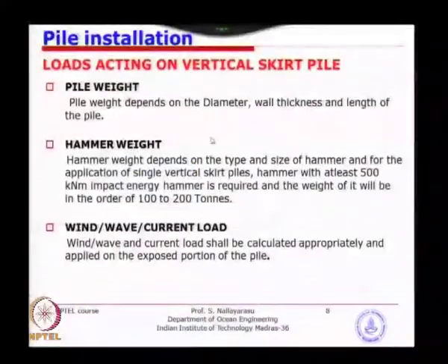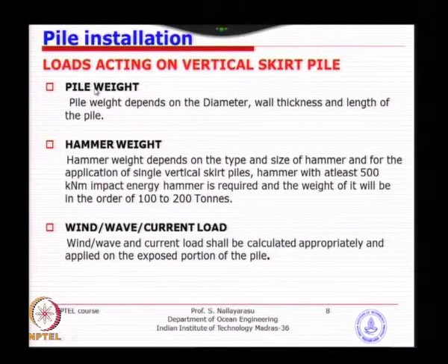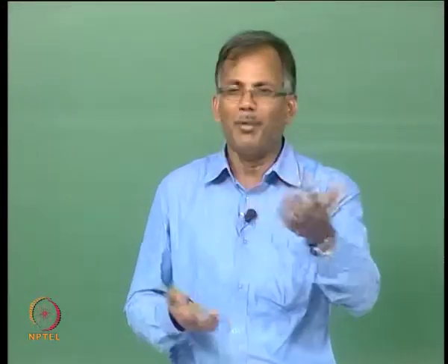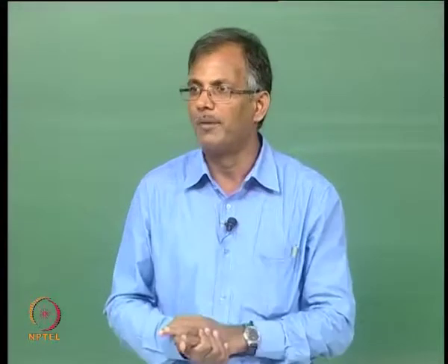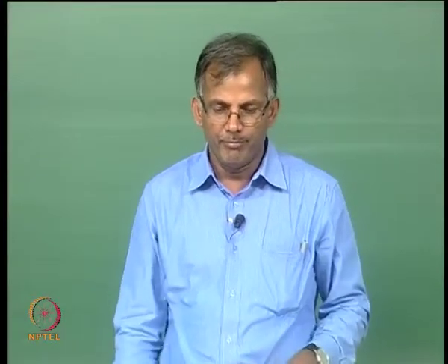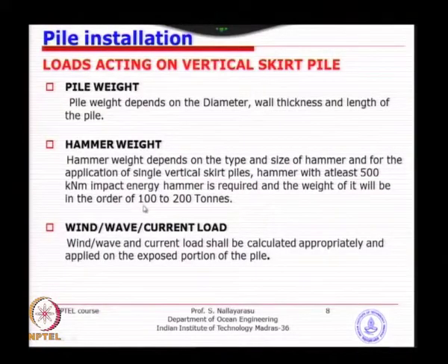So, you need to be very careful of finding out where is the center of gravity of the portion of the pile sticking above, and that much of bending moment will be applied on the support point. Hammer weight, for sure not a small number to be ignored, and if it is a small hammer, anyway you can't drive. For example, if you are driving an onshore pile system, maybe you have a 10 ton hammer, 20 ton hammer, smaller penetration, smaller diameter piles, whereas we have very large penetration and the diameters are very big.